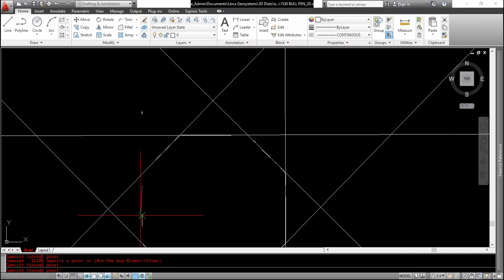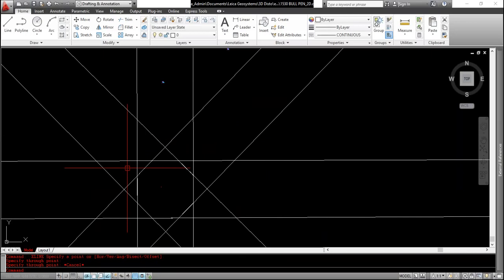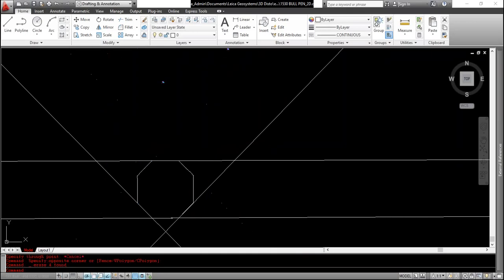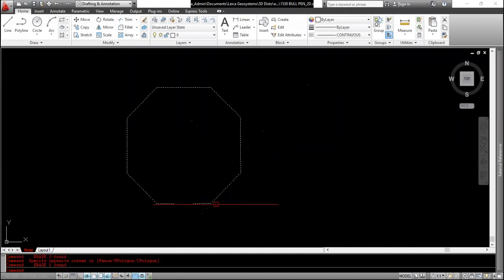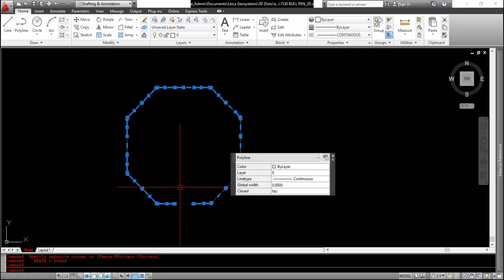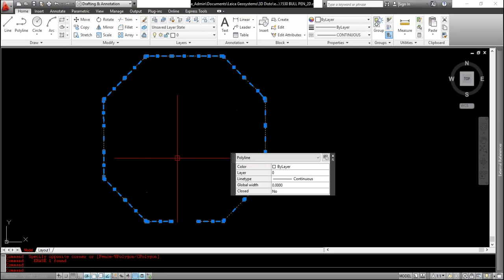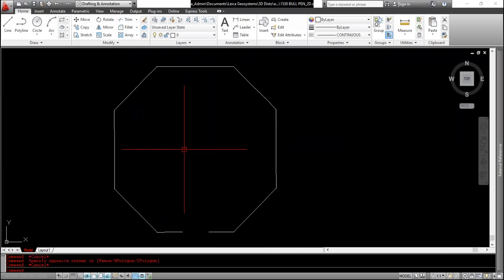and then taking these and combining them together and then doing that offset of the 24 inches deep so that the outside edge of the countertop is clean and smooth, and then the inside edge could be scribed to the wall. That's kind of how I'd go through the CNC process of this. But for right now, we've just created a joined polyline, which is what we need to start with, and then you can go from there to get your CNC programming done.